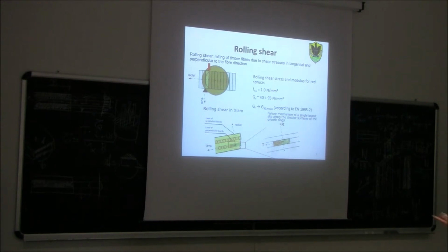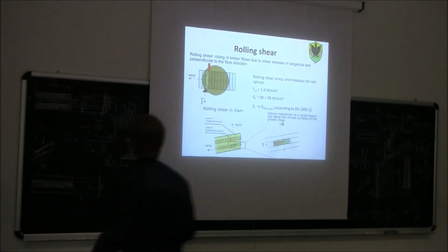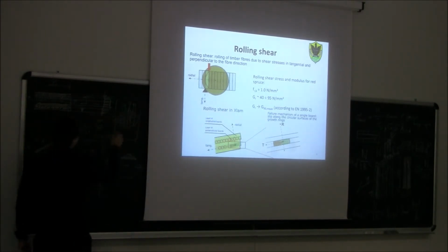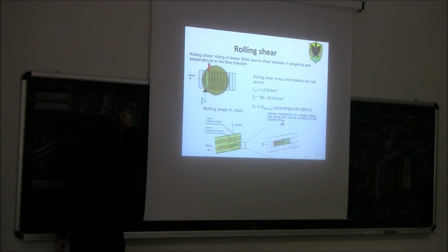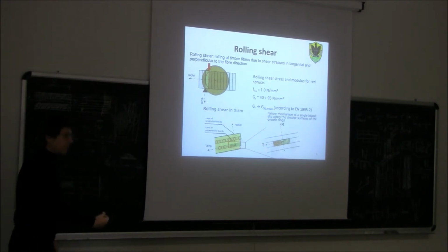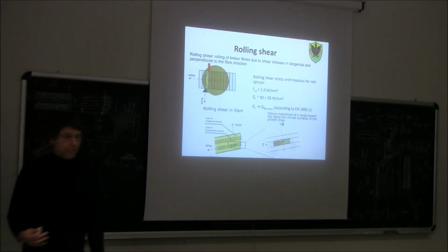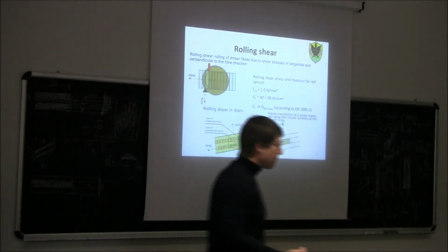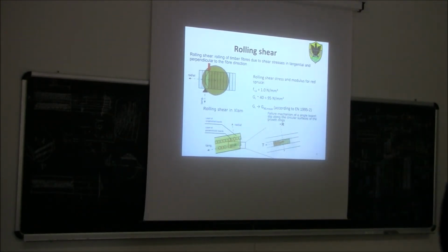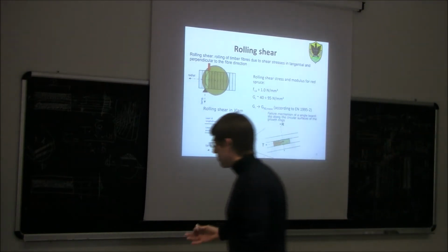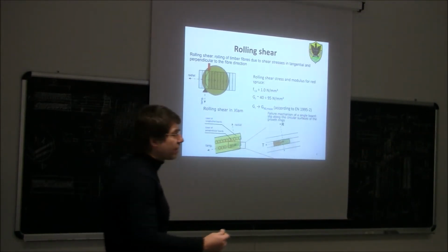However, the shear resistance is much lower if the shear plane cuts only the middle lamella, like in this vertical plane. And we also said that in this case, it's not the same having a plane which is oriented along the radial direction of the load or along the tangential direction.